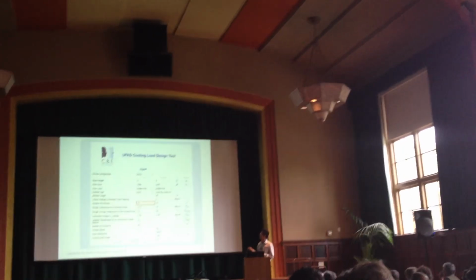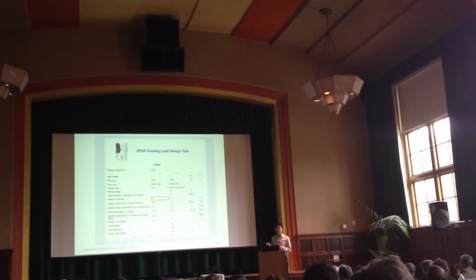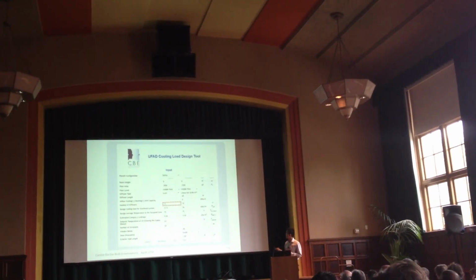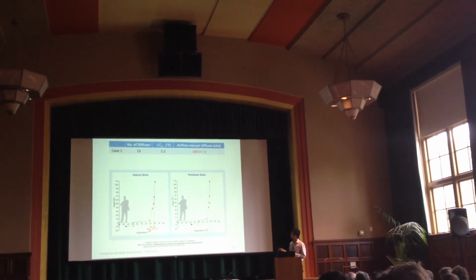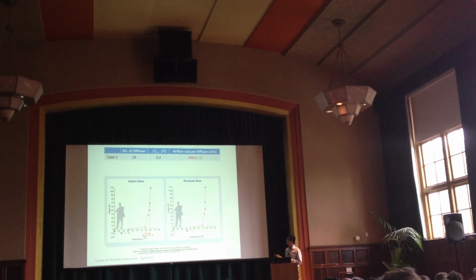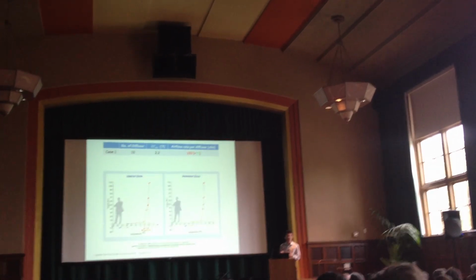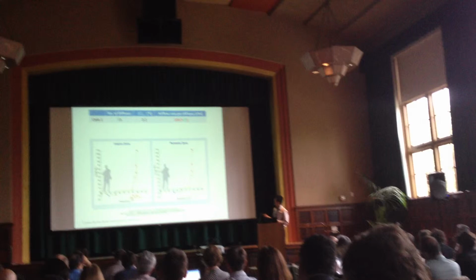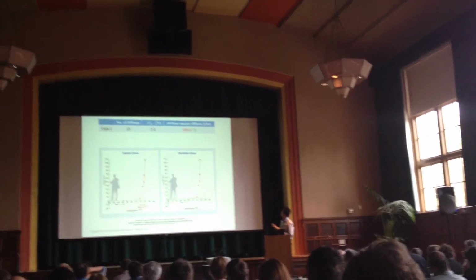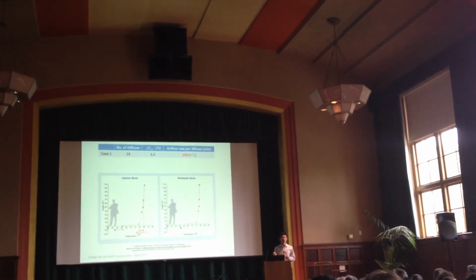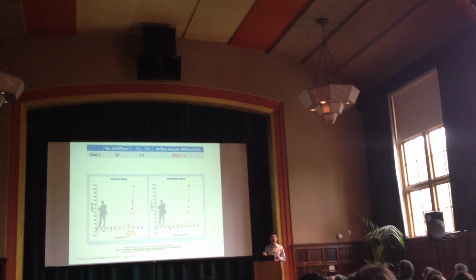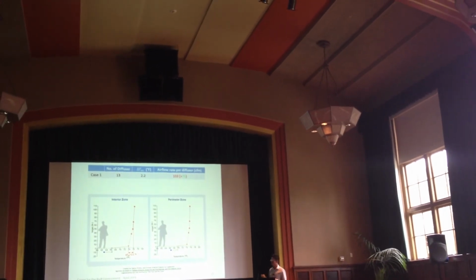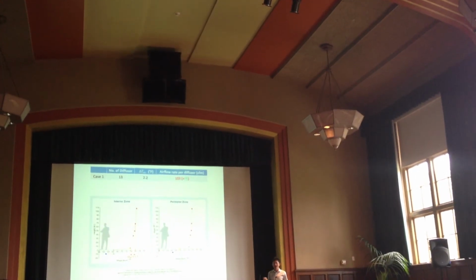Now we're going to look at the interior zone. We start with 13 swirl diffusers in the interior zone, and let's see the results. So we have 2.2 Fahrenheit degrees of stratification, which is good. But one thing we notice here, the airflow rate calculated per diffuser is 100 CFM, which is more than the nominal value, which is 75 CFM per diffuser. So we don't want that to happen.